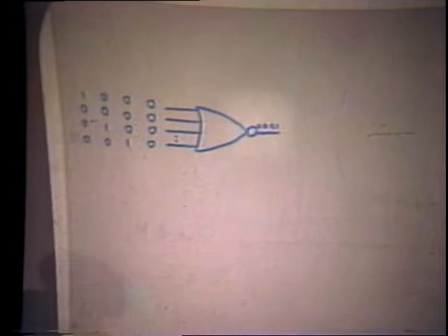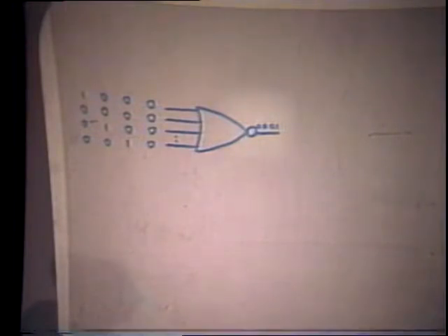So basically, to test out the test vector set for a PLA, we don't need anything fancier than this shifting 1 test vector. And that can be very easily obtained by putting in a non-linear feedback shift register. Now, what we talked about most of the time this morning was the linear feedback shift register, and they are usually capable of providing all input combinations, but we don't care for that in this particular case. We just need the shifting 1 test vector.